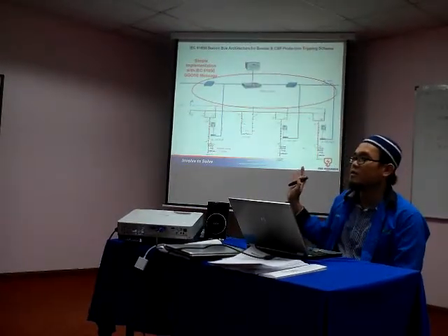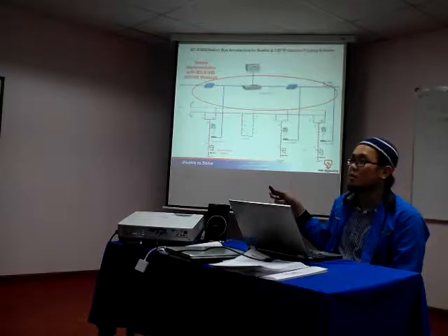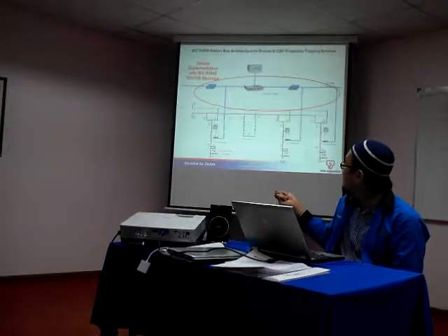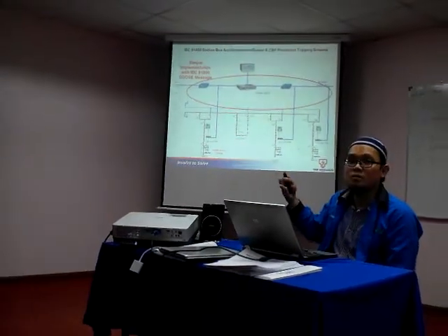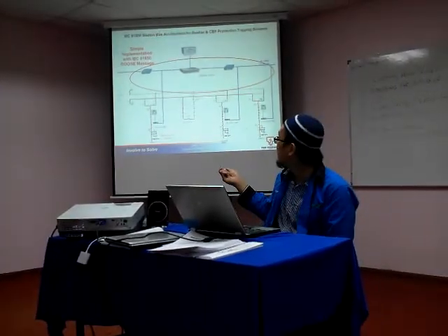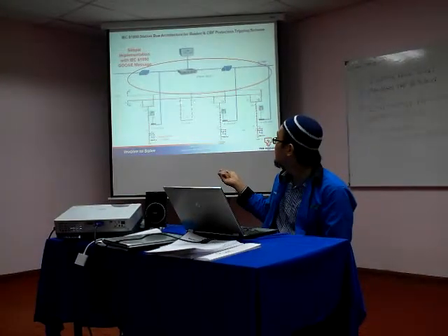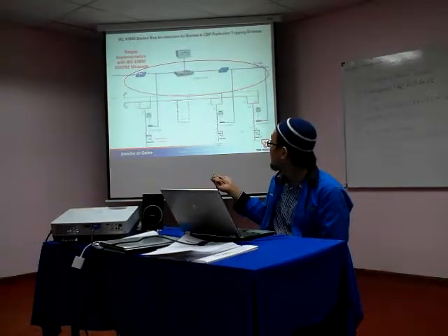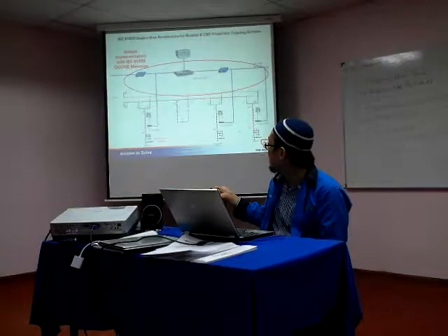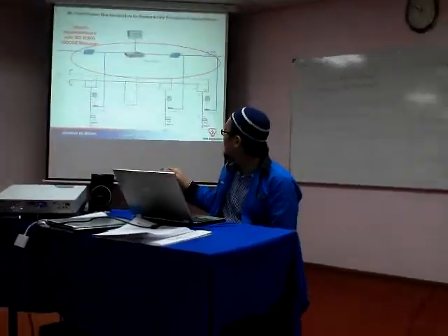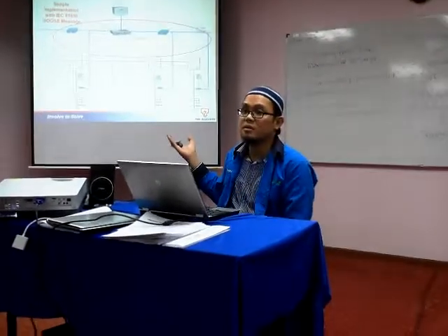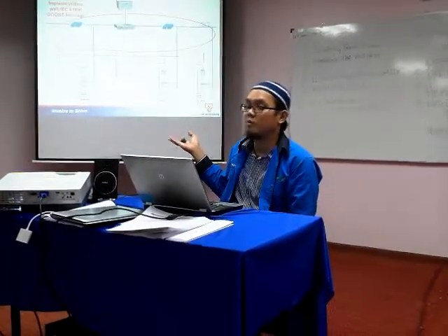This is a typical TNB substation, and you can imagine how much wire can be replaced by the Ethernet cable using IEC 61850 GOOSE messages here. This is a network switch, this is an Ethernet cable, and this is a relay that complies with the standard. All the substations use this very simple architecture for the scheme.